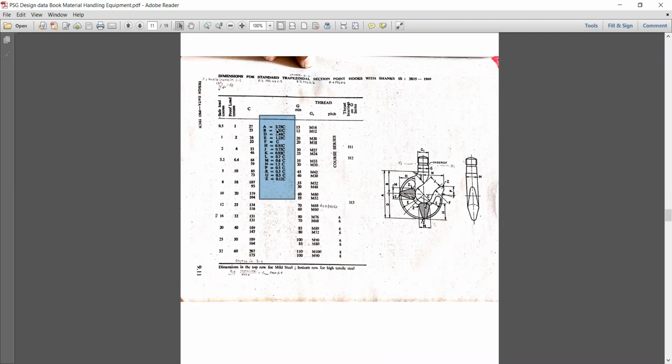So A is equal to 2.75 C. According to that you have to find all the related parameters, so that you can easily find the curved beam value, and the radius of curvature which we need for further calculation. By using this you can find all the dimensions. Okay, let's go with the design.